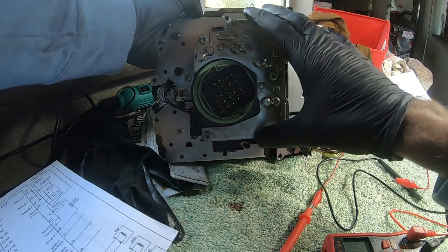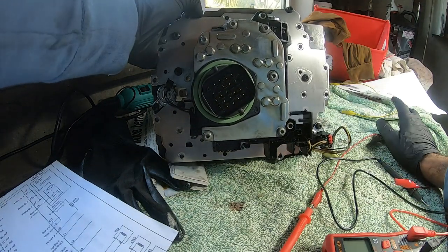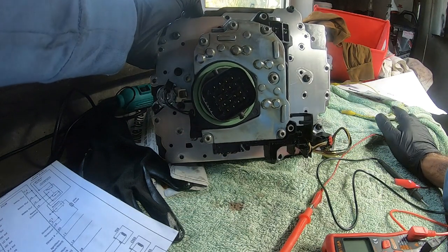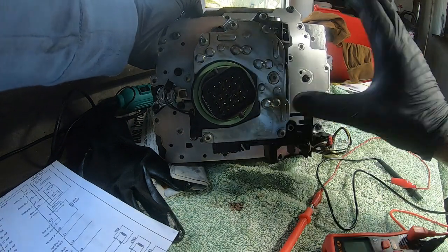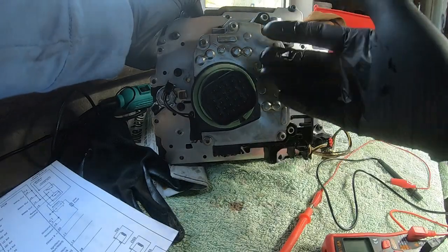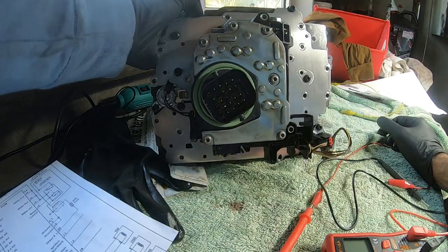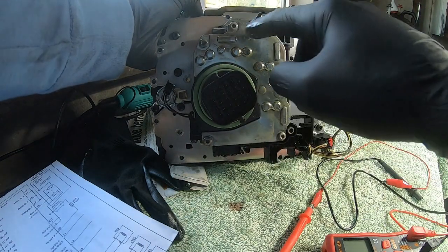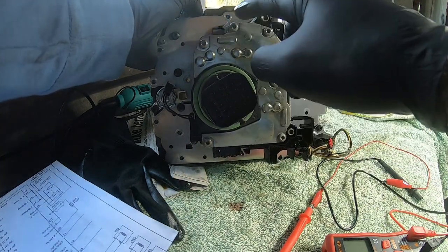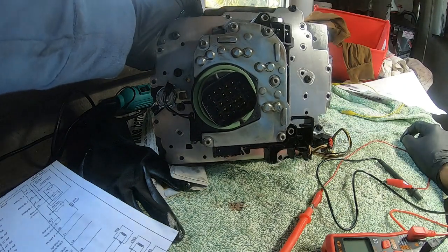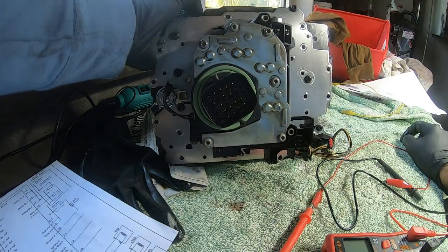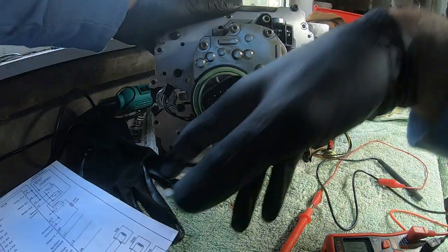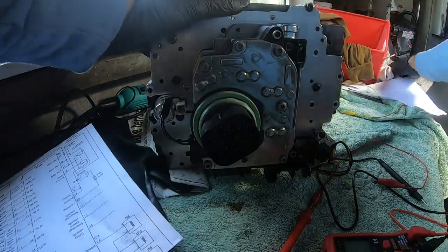So when you are trying to remove it, immediately 2 things can fall off, because it is always mounted vertically, which means that the plate is vertical. You remove it, some things can fall off, and those things are the springs behind it, and the dowels through which these bolts go onto the valve body. So just try to be cautious and be ready for those falling springs and dowels. So let's see if we can remove it.